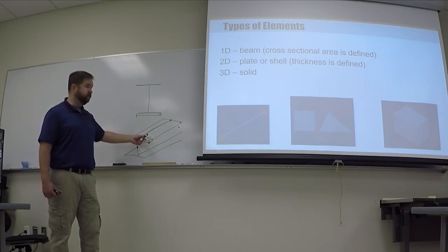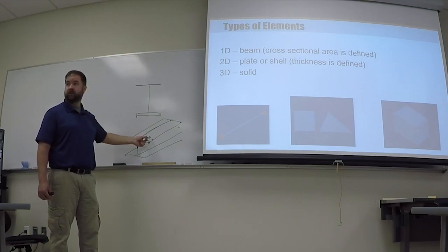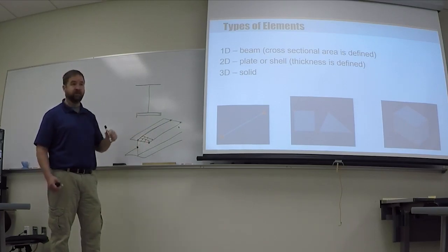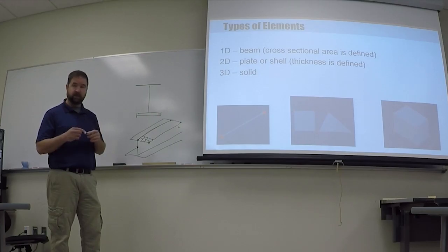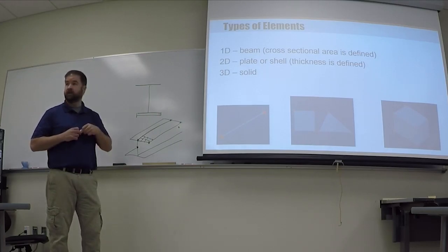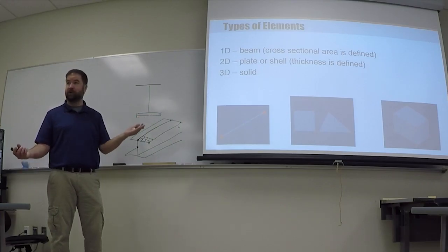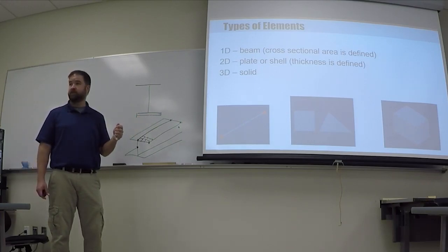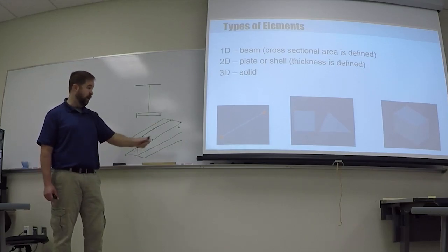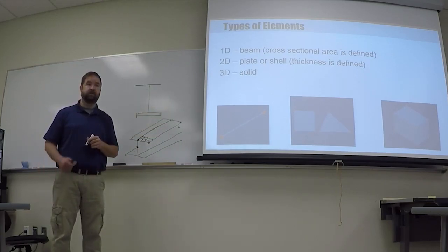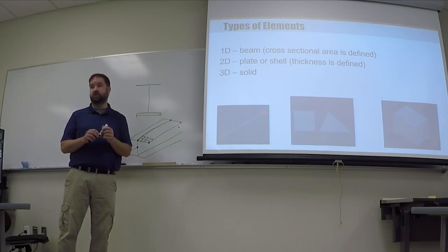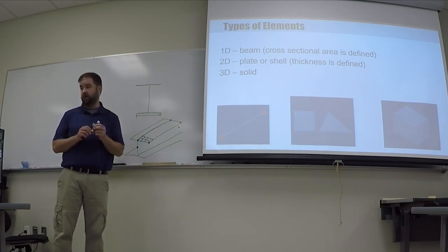All right? So millions, possibly even billions of elements times the number of degrees of freedom, and it rapidly gets, can you do it? Absolutely. Do you really want to wade through all that data? Well, there's absolutely no reason to. I mean, model it as a 2-dimensional element, and you're going to get pretty close to the right answer. Now, you're not going to get all the details of every weld on the bridge. If you wanted to do that, you'd have to model it as 3-dimensional elements. But it would be a hugely inefficient use of your time and computer power to do that.